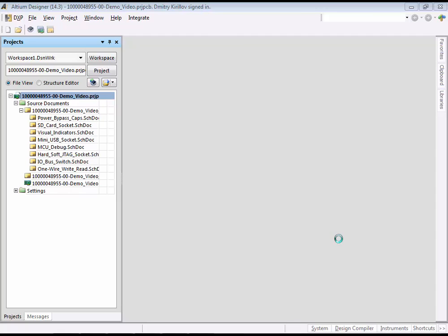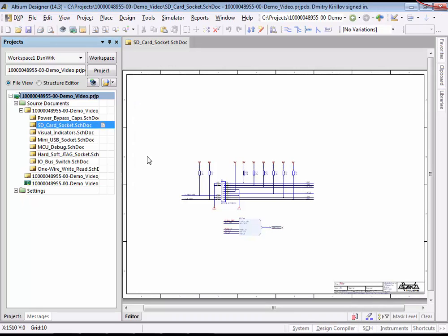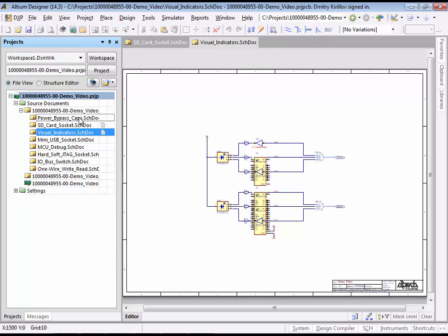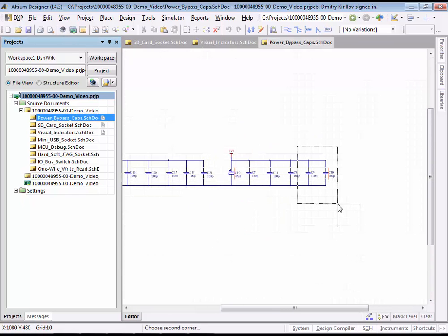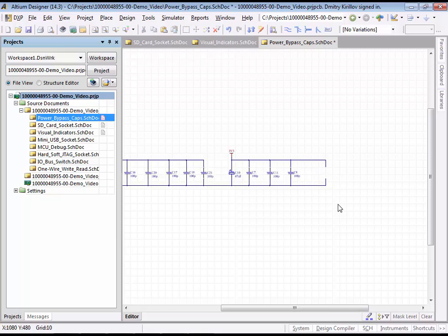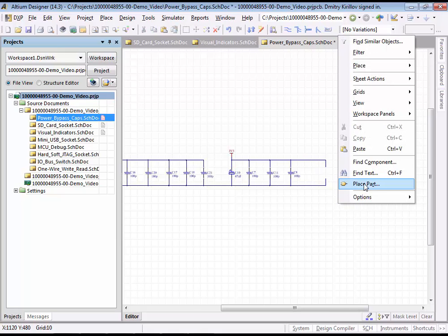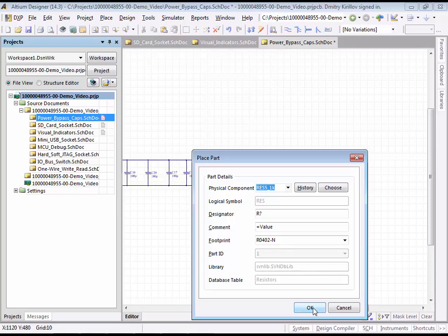After confirmation with the OK button, the design is downloaded and renamed according to the new revision and the identification number. The next step would now be to change the design and upload it again with the module Save to the PLM system. Therefore, we delete two capacitors and place a new resistor into the design.